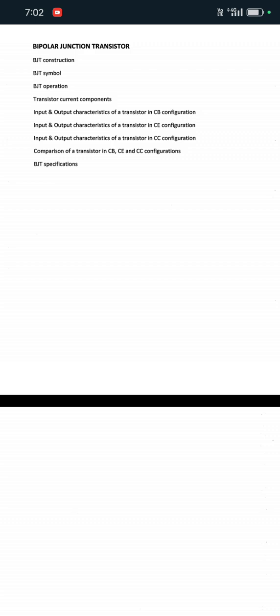diode. So what is diffusion, and what is the depletion layer? When a p-n junction is formed, the n region loses free electrons because these electrons are diffused across the junction. Hence they form a layer of positive charges near the junction. Similarly, the p region loses holes because the electrons from the n region combine with the holes, so they form a layer of negative charges near the junction. These two layers of positive and negative charges form a region called the depletion region.